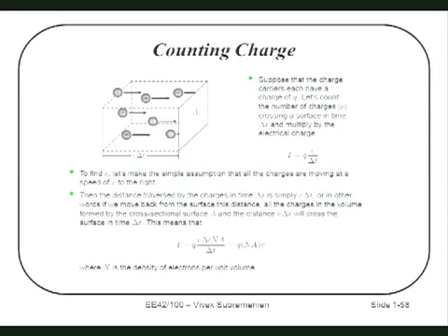Okay, first, why is Q here? What is Q? It's the charge per electron. If I'm taking Q out, that means what I'm left with over here is the number of electrons going through a plane per second. And I multiply by Q to get charge per second. Okay? So this is the number of electrons per second. Okay? The delta T and the delta T accounts for the fact that I'm integrating. So I'm waiting from 0 to 1 second, and then I divide by 1. If I waited from 0 to 2 seconds, I would divide by 2, and so on and so forth. Okay? So that's where the delta T's come from.